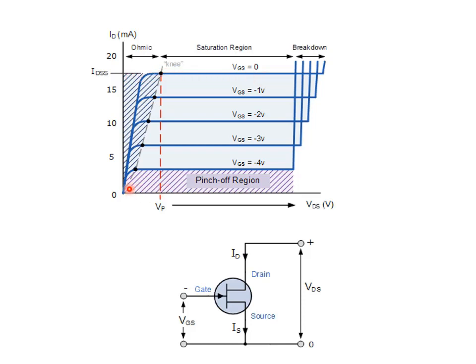So when this transistor is working in the ohmic region, the transistor is basically like a resistor, and we call the resistance of this FET transistor the ohmic resistance. And it's very easy to calculate the ohmic resistor. Let me show you. We call it RDS, and RDS is very easy to calculate. It's going to be the pinch-off voltage divided by the drain saturation current, IDSS.